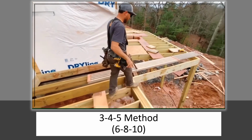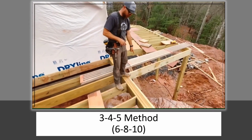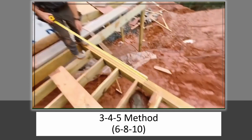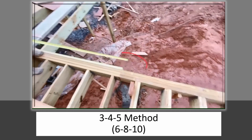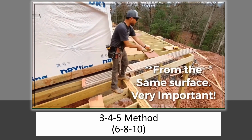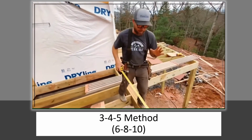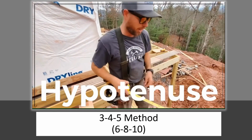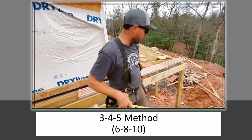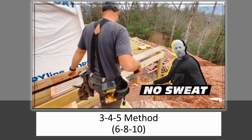So I have a fixed point out here. I can't move this in, so I can only move this in. What I've done is I've measured 6 feet from this surface out to a mark right here. What I've also done is measured out 8 feet in this direction. You can see this screw way out here, okay? Now I'm going to measure the hypotenuse, which is the longest leg of the triangle between these 2 points, and if it's exactly 10 feet, then our corner down here is 90 degrees, which is what we want. So let's check it.